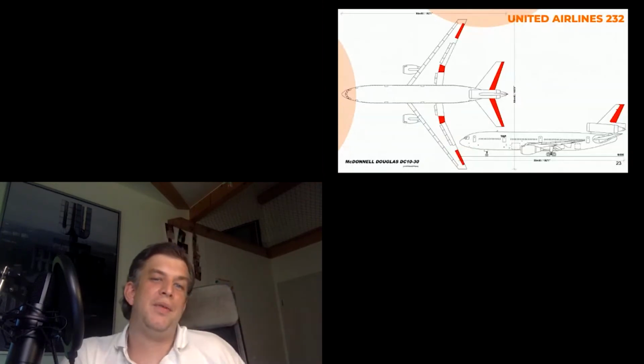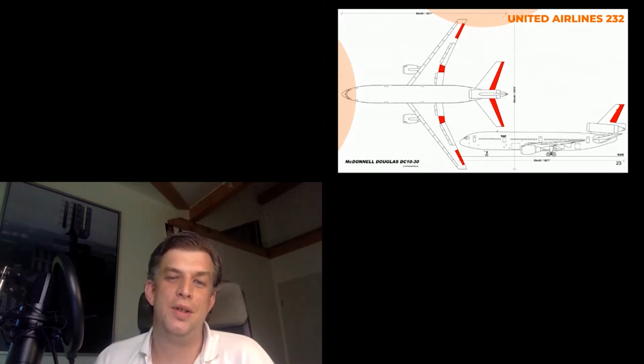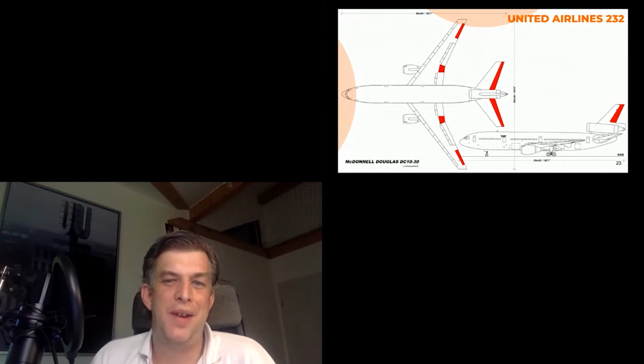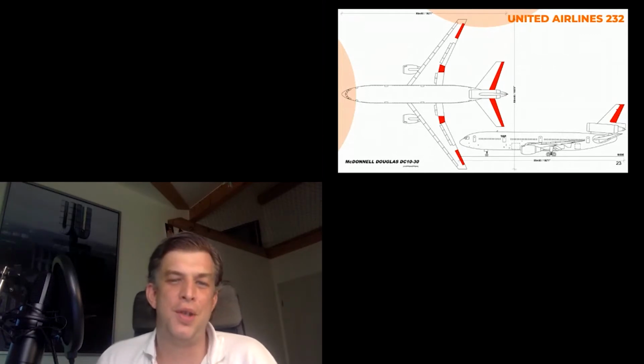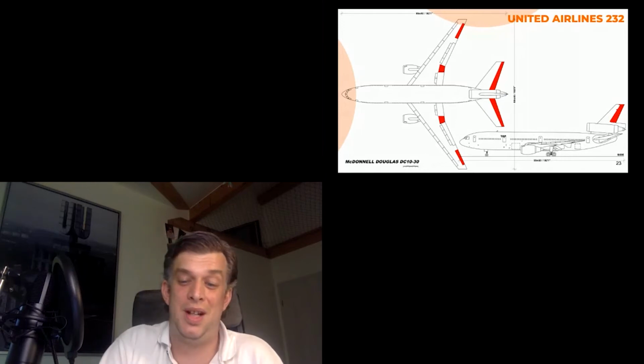The reason for that is that the DC-10 belongs to the first generation of airplanes that has no manual reversion. This means that the air control surfaces that you see in red are just too big and have so much force acting on them that if hydraulics fail, you anyhow can't wrestle them by human force. So Danny has never taken anybody through a scenario of a full hydraulic loss because there was no need for that.